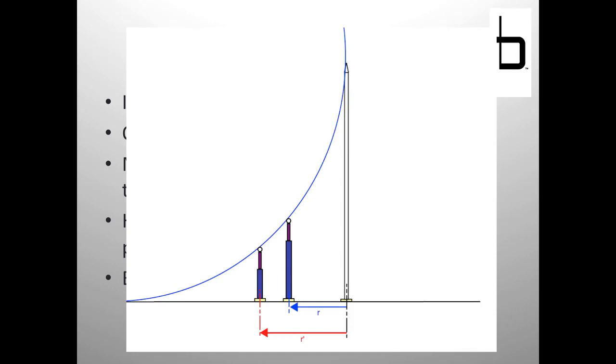assuming everything was at 30 feet, and not everything's at 30 feet, it kind of goes back to the sphere. You know that if you've protected against 30 feet, you've protected against shorter equipment as well. If you've protected for equipment that's 30 feet tall, you know that equipment that's actually 20 feet tall will fall under that protection as well. So that's a way to simplify calculations, just going for your highest equipment.